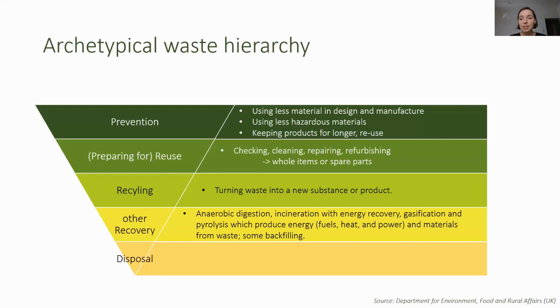Anaerobic digestion, it's basically biogas plants. That's the process they use. It's kind of a fermentation, so without the use of oxygen. Incineration with energy recovery means burning the waste, but using the heat energy that comes from it and translating it into, for example, electric current. Gasification is a process by which wastes are transformed into syngas that can then be used as chemicals or as a fuel.